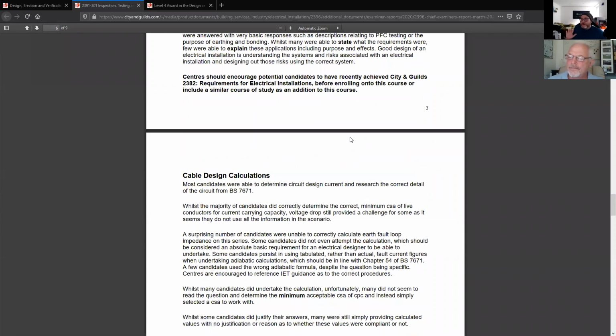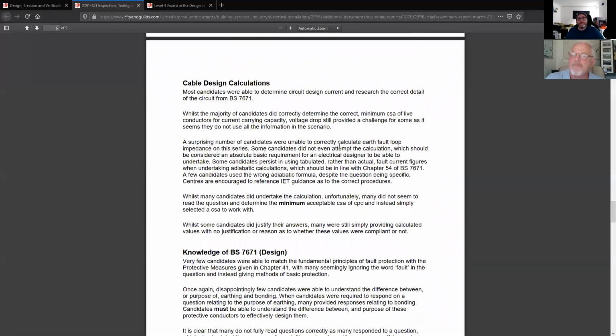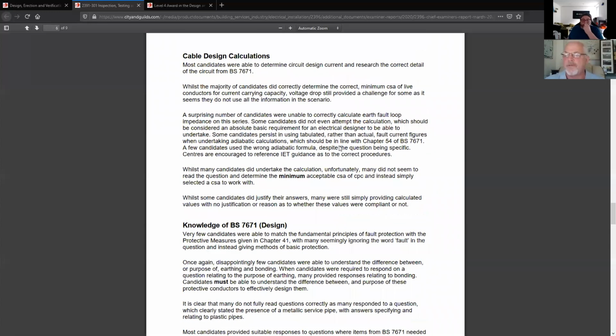I says, yeah, but the tests aren't done with one press of a button. Yeah. And you know, there is a gap. There's a huge gap in understanding with that. It's the same as when you do your ZE reading. If you do a ZE reading with your main earth conductor removed from the main earth terminal, then you need to reconnect it before you do your earth fault current reading. And people don't understand. You know, I talk to people and they think, well, what's the difference?